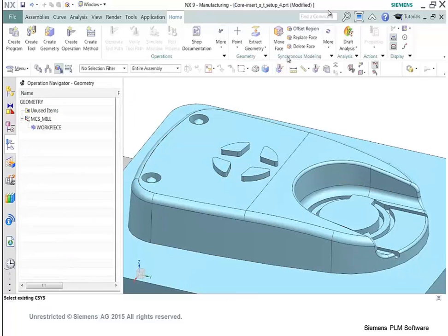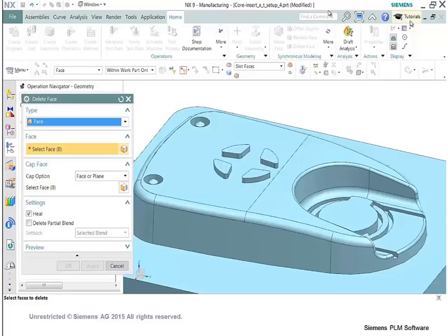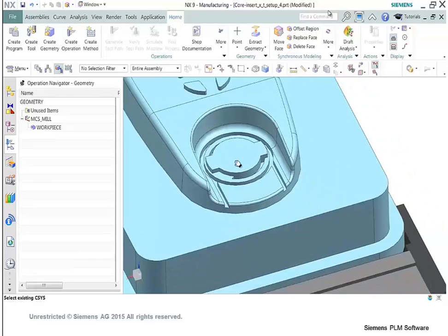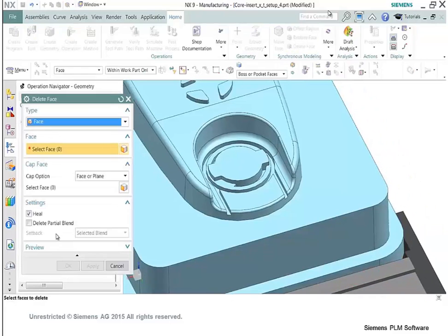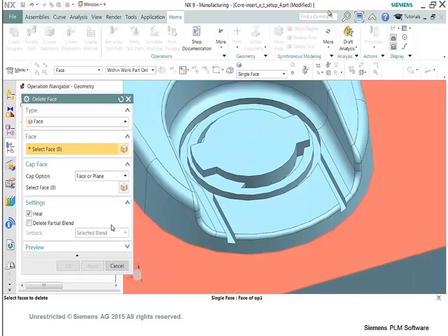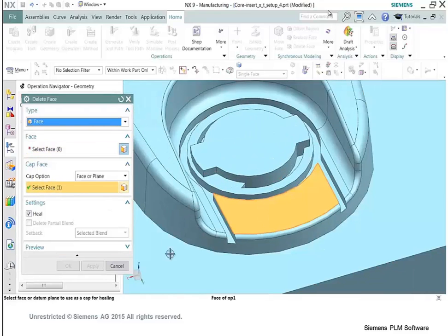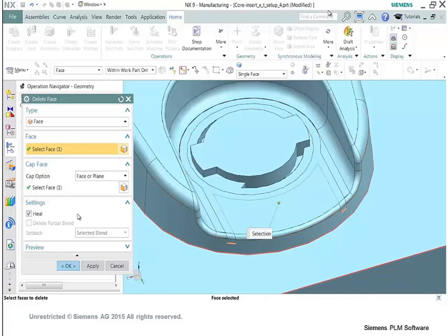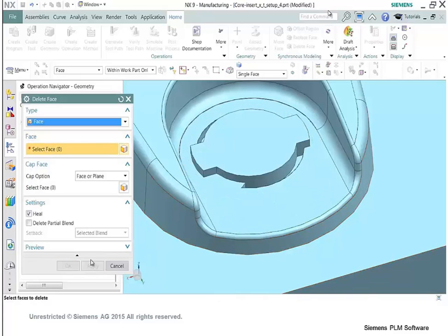Now let's go ahead and close the 2 little pockets up there. We can close those off. And again, it just gets absorbed into the geometry of the part. Again, all these small little slots out here kind of would wreak havoc when you're trying to go in and machine that or finish machine that. Right, so you'd be picking all kinds of edges and things. Well, this way it's really quick. We just take those 2 and it closes all of that up. And then we'll go back and do the same thing, and I'll close those other 2 up.